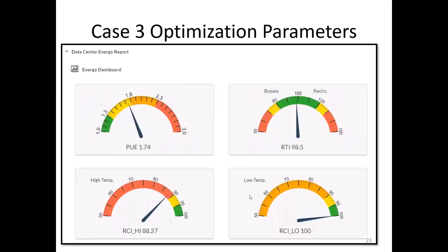What does this one tell you, Magnus? I'll let you narrate this one while I search for the chat box window. Well, now we can see that in the second chart up to the top right, the airflow balance is close to balanced. We're supplying as much air as is drawn into the servers.